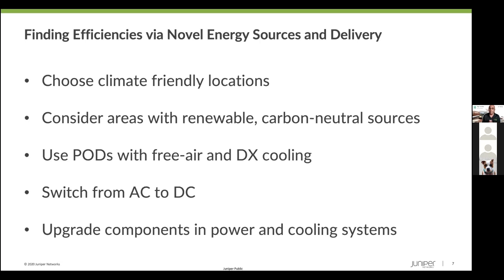So that's where I think these technologies are more important in terms of being able to build energy efficient data centers. Switching from AC to DC has two advantages. First of all, it removes lots of conversion steps, reducing losses. That means you improve energy efficiency. And secondly, once you reduce the amount of power, it is estimated that you can get about 15% savings by using DC power versus AC. Less 15% power also means less air conditioning, so you also save energy in the air conditioning system.